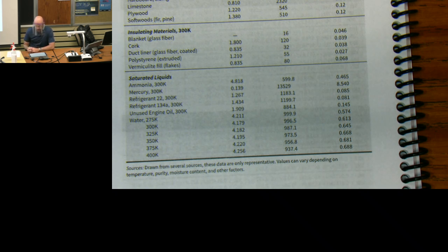Now let's talk about the heat transfer. If we put this tank out there, and it's a bigger tank, and we threw this small piece of metal into it, and we put our hands on the outside of the tank, we probably would not feel heat leaving the tank. The problem statement says it's a well-insulated tank, so that takes it out. But we could probably make the assumption anyway that this is not going to heat the tank up so much that we're going to feel a lot of heat coming out. So that goes away. And so now we just have delta U is equal to 0.